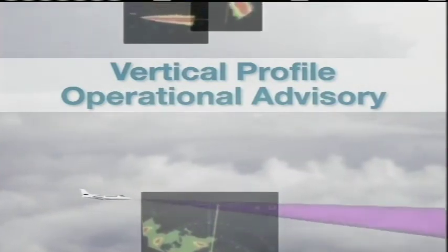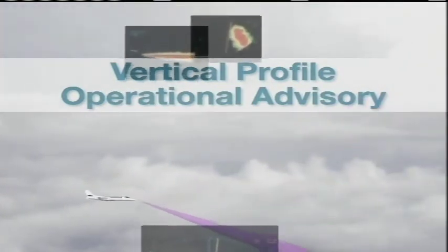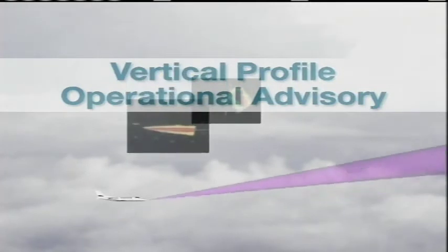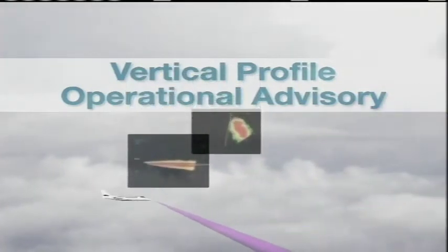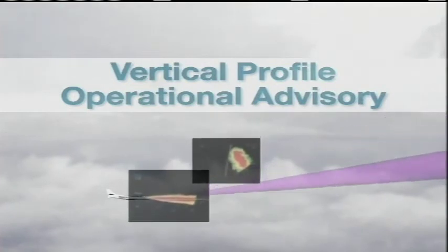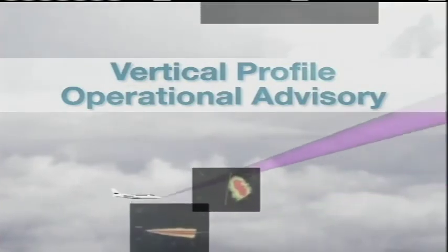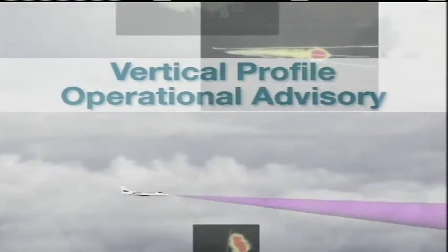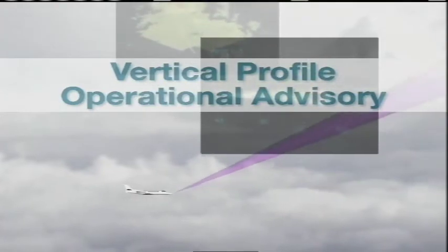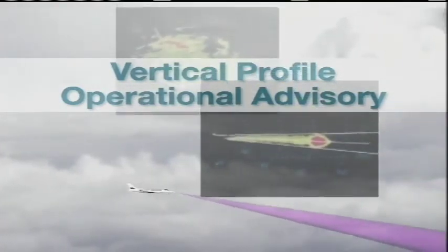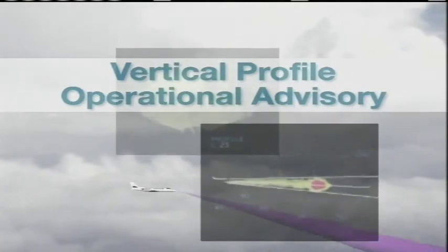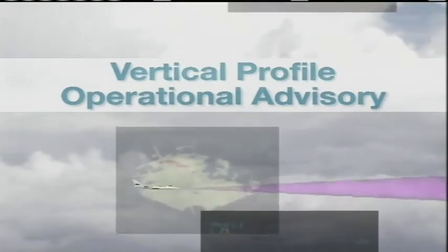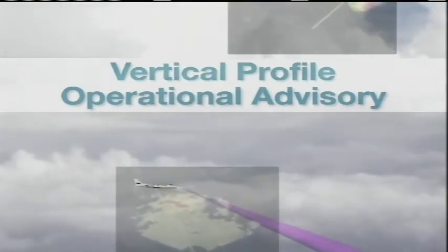The RDR 2000-2100 radar greatly simplifies the task of determining vertical characteristics of a storm by pictorially displaying a vertical slice of the cell and showing its radar height. The accuracy of radar height is limited by beam illumination and range resolution. Since cloud tops composed of ice crystals or dry hail, both of which have low radar reflectivity, or storm-associated turbulence without precipitation, may extend several thousand feet or higher, appropriate caution must be exercised when attempting to overfly a cell which exhibits high radar reflectivity or extends above the flight level.